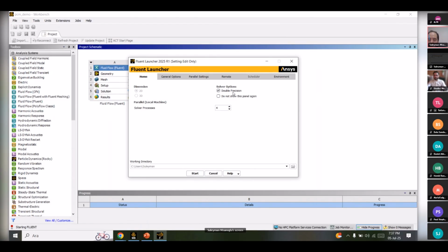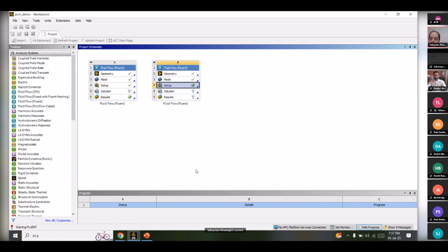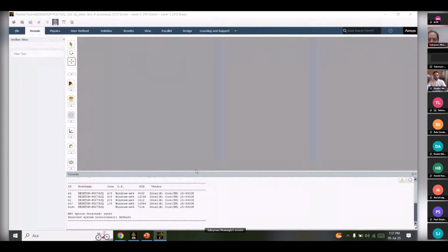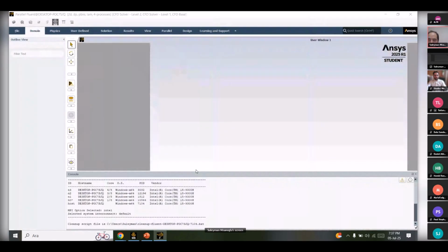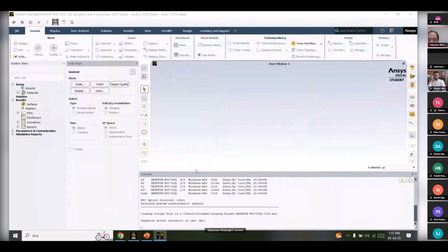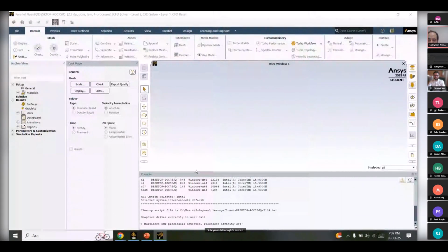This means the program will consider 16 decimal places after the comma instead of 8. During the phase change, there is a concept called liquid fraction, which is the ratio of liquid mass to total mass. The liquid fraction changes very, very slightly during the phase change process. So 16 decimal places help us get accurate results.